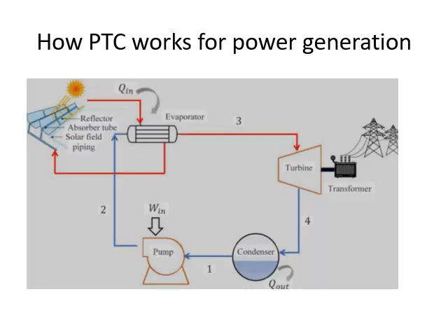In this diagram, we will see how the PTC works for power generation. I believe you can remember the vapor power cycle, right? The Rankine cycle, where we used to have a boiler and the boiler would be sending the superheated steam to the turbine. The turbine will be generating electricity or whatever form of work that is required. Then the rest of the exhaust steam will be coming to the condenser to get condensed. Then it will be pumped back to the boiler pressure again.